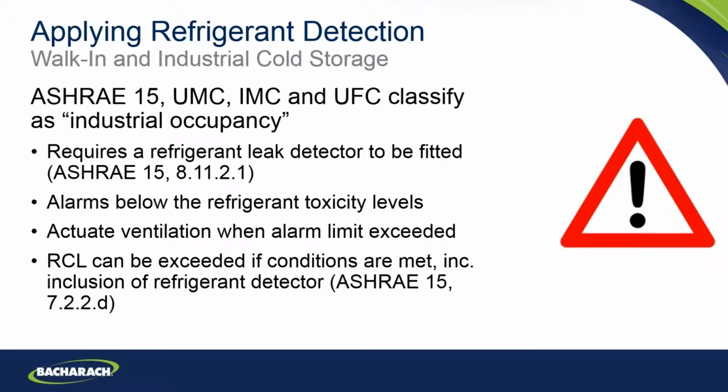This applies particularly strongly in walk-in freezers, walk-in cold rooms, and in industrial cold storage facilities. ASHRAE 15 and the mechanical and fire codes all classify these areas as industrial occupancies, and they do require a refrigerant leak detector to be fitted. The important thing there is the alarms must be below the refrigerant toxicity levels. So there's no driver here for leak rate reduction. Again, we are talking purely safety here.